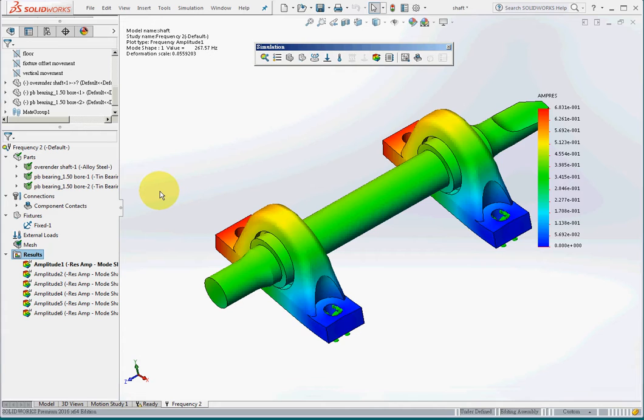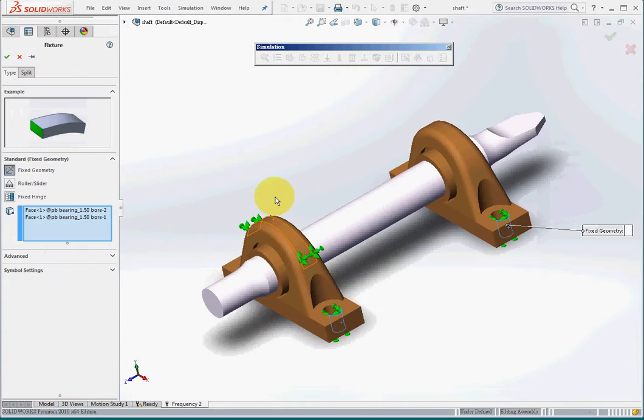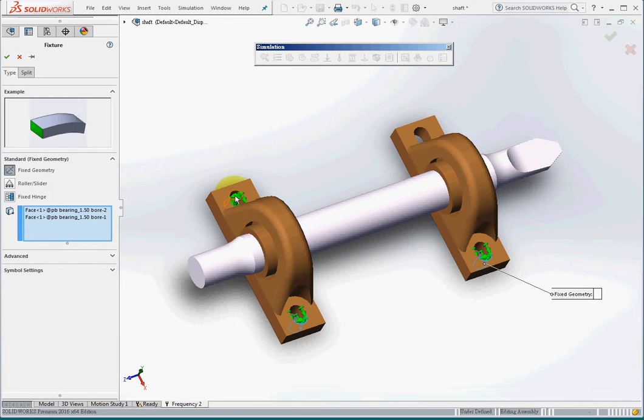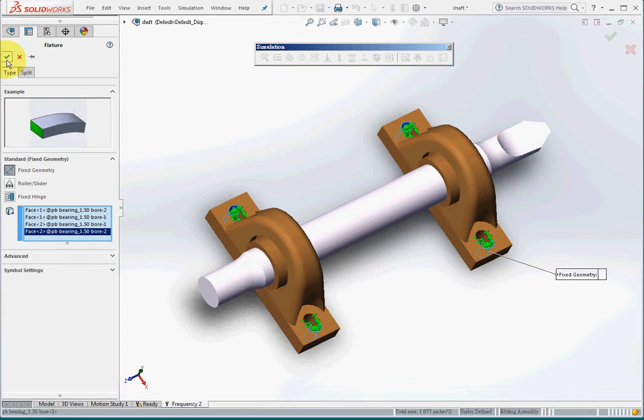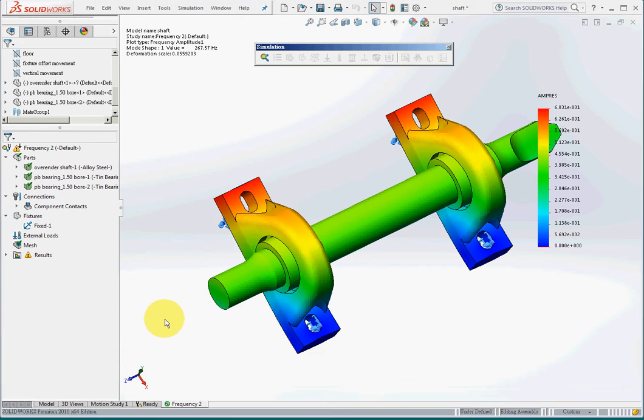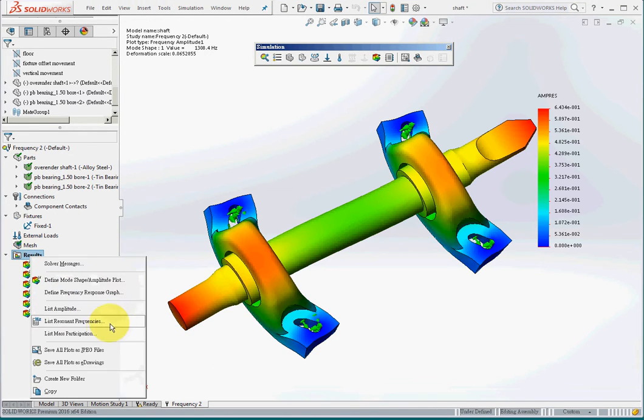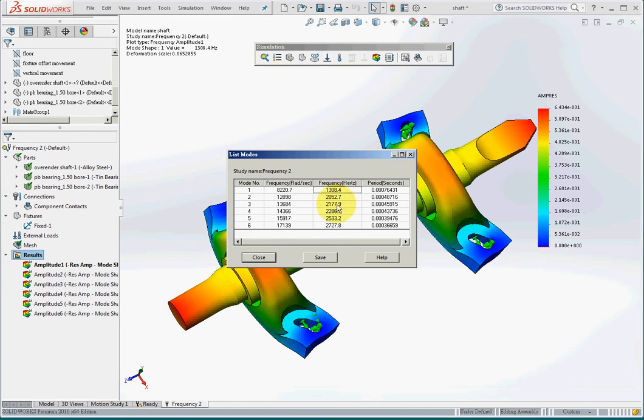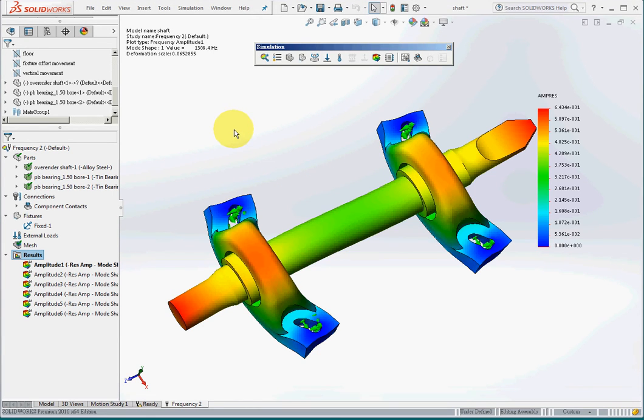The stiffness, the rigidity of the structure will increase by fastening all the fixtures. For example, this is an old machine, and if I fix these holes again, the rigidity will be higher and the frequency of the machine will go back higher. So if your machine gets old, you get a lot of noise. Theoretically, you can fasten all the fixtures and remove the noise.